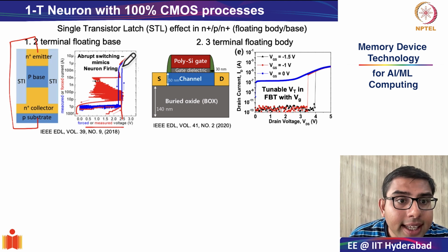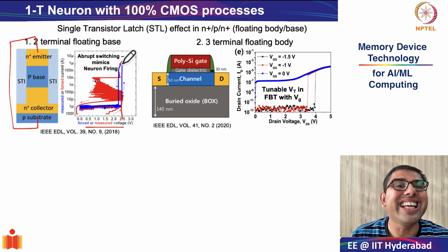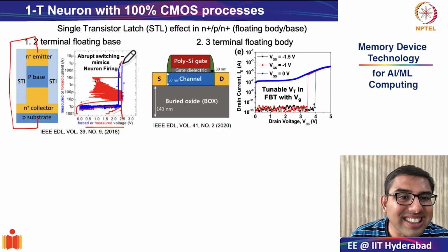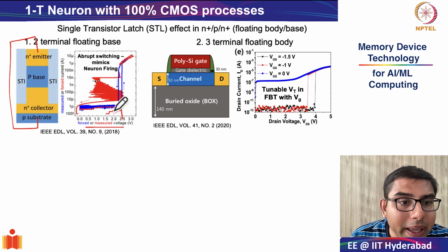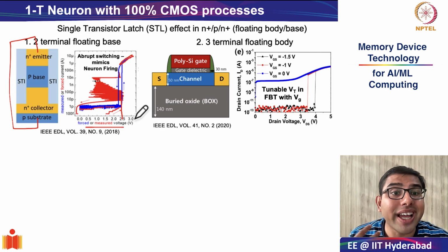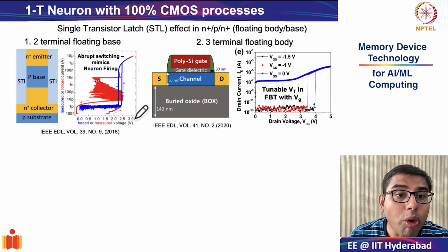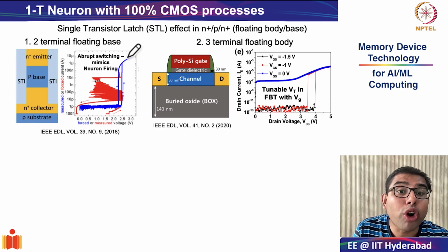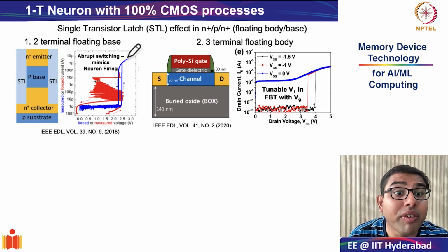But you see that after it reaches the low resistance state, it stays in the low resistance state if you keep increasing the voltage. And this is where the latching effect comes from. So it has latched on to the low resistance state. However, it is very different from a non-volatile high resistance to low resistance switching that we have seen in our eNVMs. Why is that the case? This is volatile switching. Why?